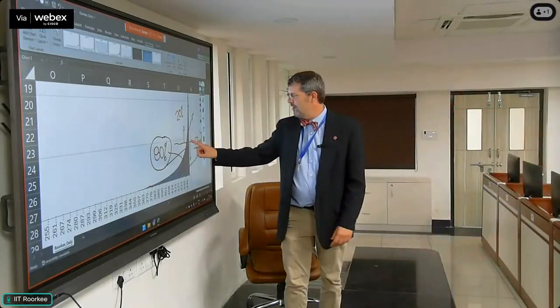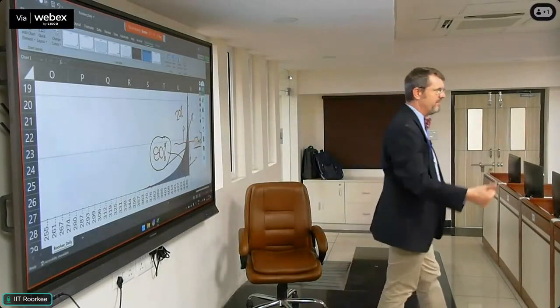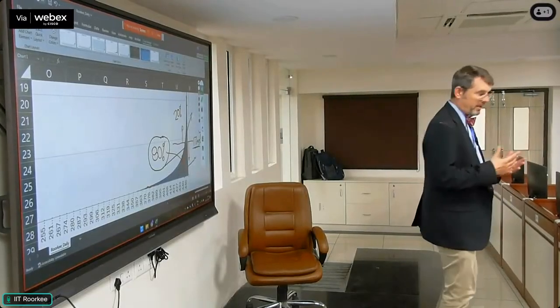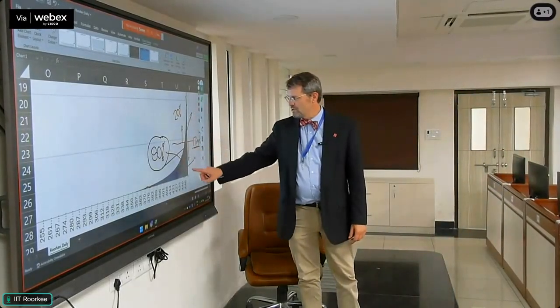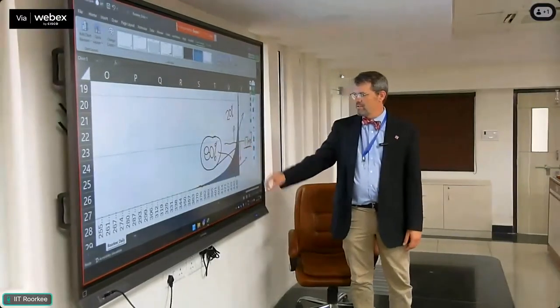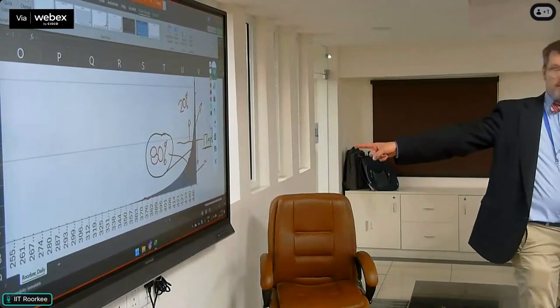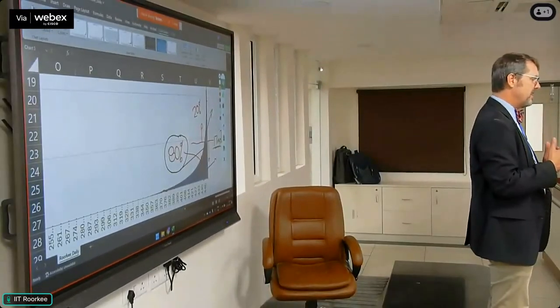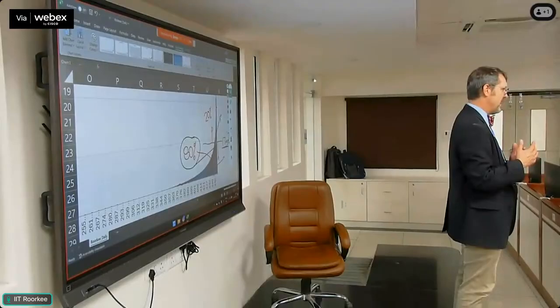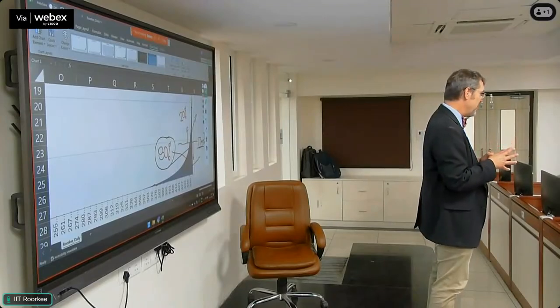And then I counted all of the storms that exceeded 17 and multiplied those by 17, right? Because the storm control measure, even if it's a massive storm, is still subjecting at least 17 millimeters of it to treatment. And so when I did that, that's how I got these values. So that's the right way to do it, but it's kind of inefficient without me having a good equation set for the spreadsheet. So if y'all could go ahead and try to figure that out.